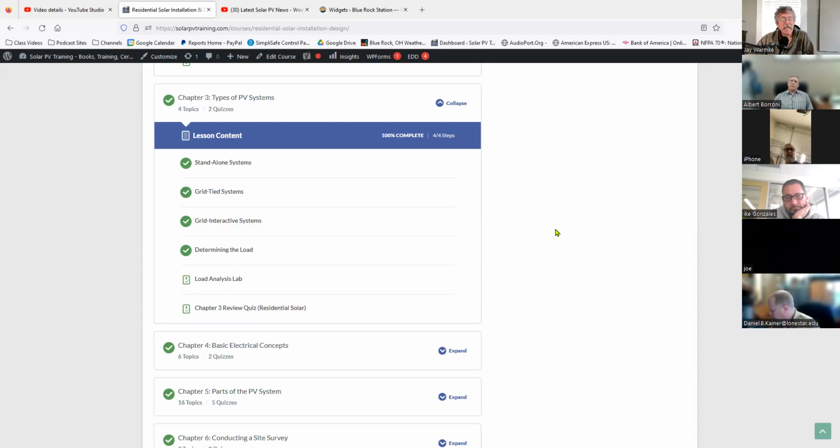Now, it's constantly sensing the grid to see if it reestablishes itself. If it does, then it waits for 5 minutes because sometimes the grid will come up and then drop right back off again. So it doesn't want to keep switching until the grid is stable. But then it'll go back into grid mode. But it then allows you to draw power from your electric vehicle as your battery backup system.